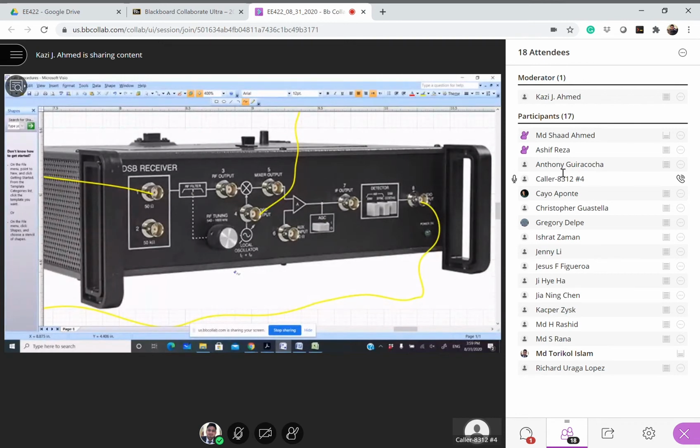So you try to tune your local oscillator to the incoming signal so that you can only pick that signal, right? So when the local oscillator becomes 1455, your receiver is tuned to the incoming signal. Does that make sense, or do you get the point?